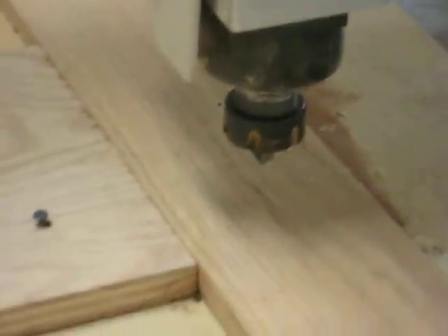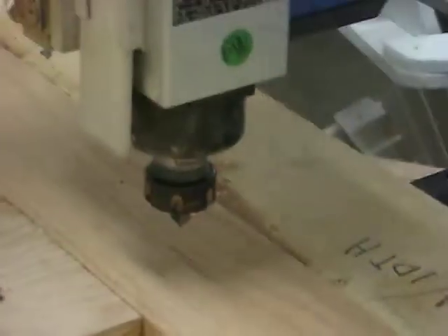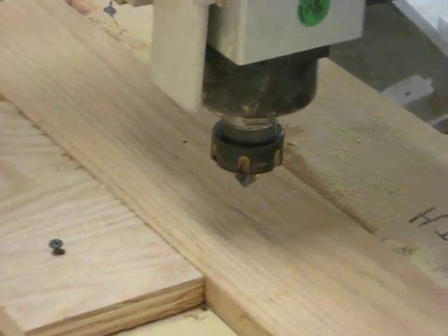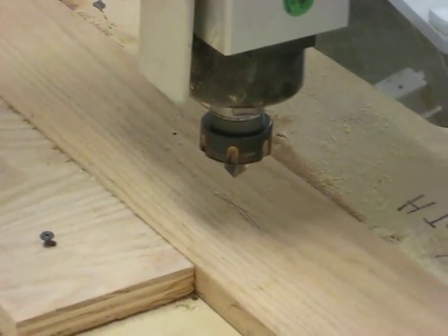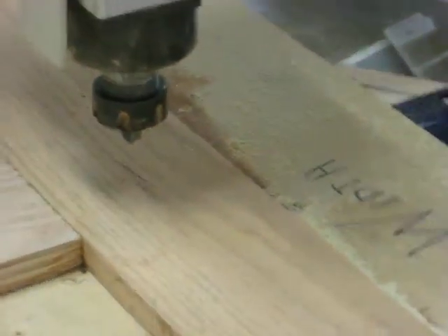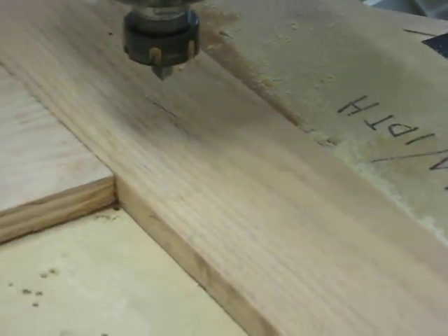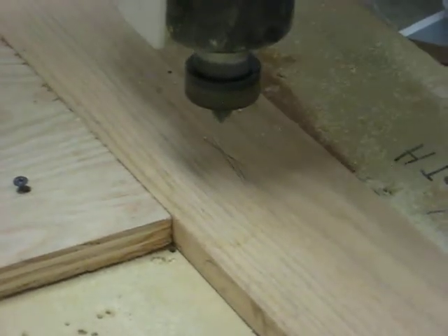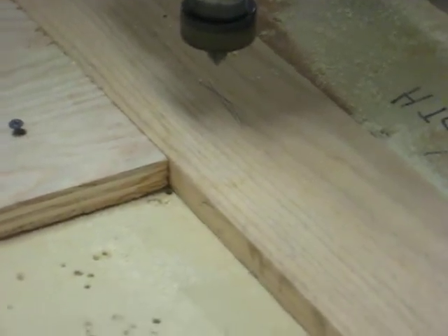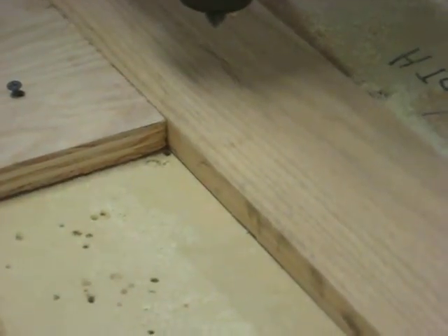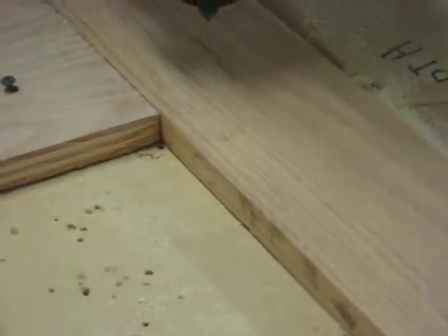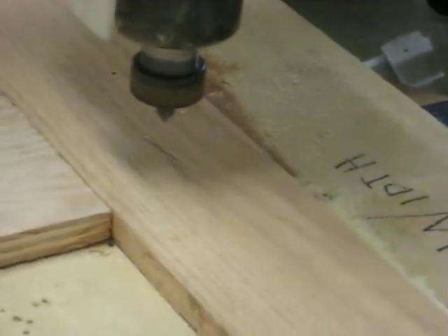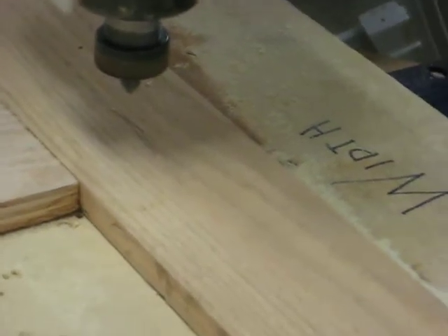Now he's going to ask it to do the part. So he's actually programming the ShopBot machine to go ahead and start. Okay, he's turning it on. It always starts from the center, or the 0 axis. So it's zeroed out at this point, except the Z is a little bit higher, and you want it higher so it doesn't cut into your product. Alright, go ahead and hit go so we can start cutting.